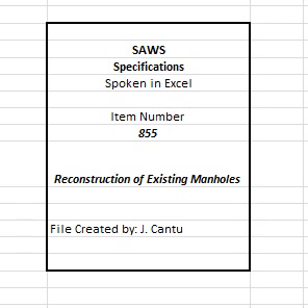4. Prior to performing the test, the contractor shall plug all lift holes and exterior joints with a non-shrink grout and plug all pipes entering the manhole. 5. No grout shall be placed in horizontal joints prior to testing. 6. Contractor shall use a minimum 60-inch LB torque wrench to tighten the external clamps that secure the test cover to the top of the manhole.